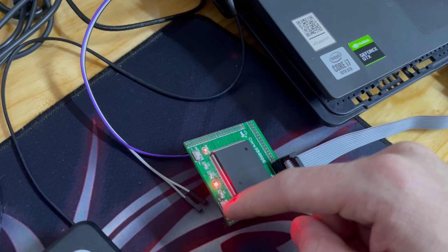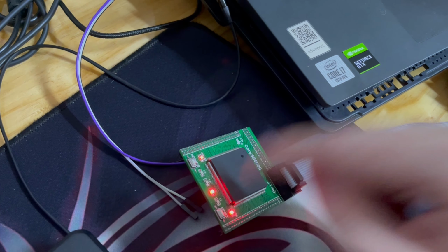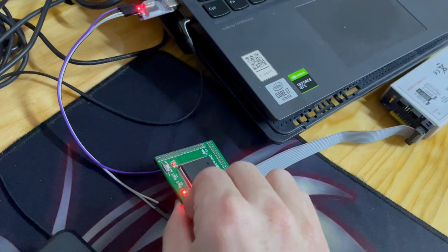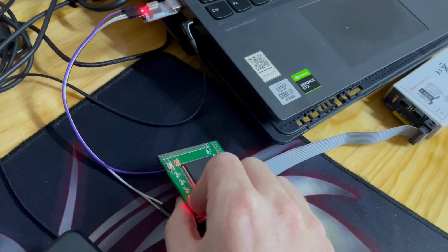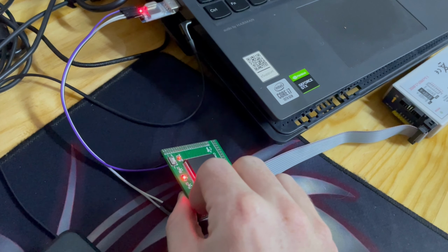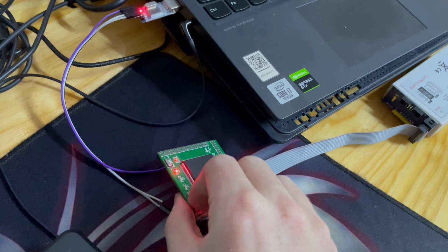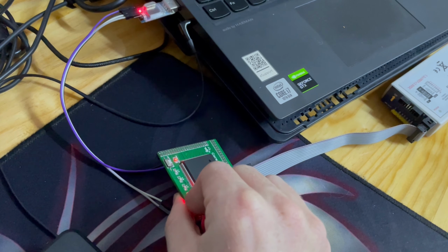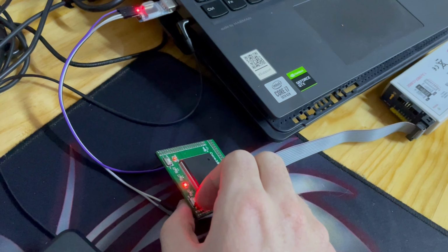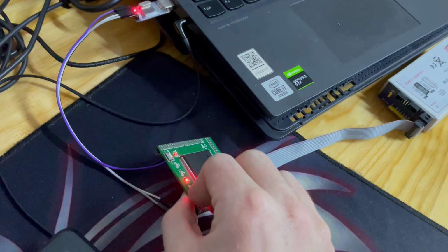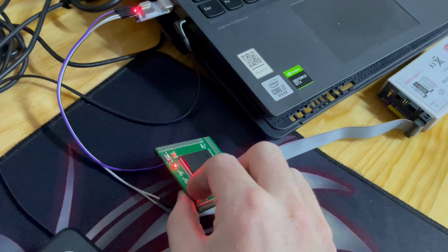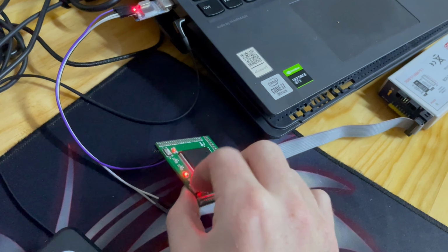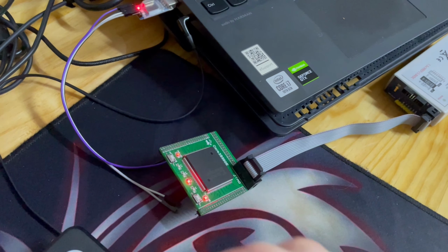So we probably should have put a NOT gate onto the reset button as well, but we didn't, but it's fine. Still works just fine. Another indication is that if I press the reset button, nothing happens, but once I release it, it switches. So that also means the reset button is definitely active low.